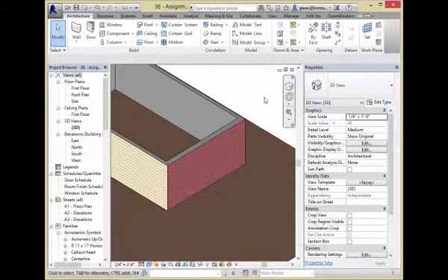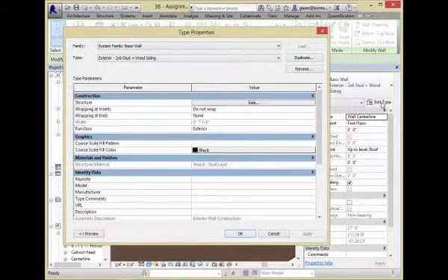So we have some different wall types set up, but let's talk about how you can customize that. Because you may have in your mind some fantastic idea. Oh, I saw these really groovy composite panels. Some other idea. And you want to put yours in instead of something I've given you. So how you do that is as follows. You can choose any old wall and edit its type. So I can switch types, or I can actually edit and change.